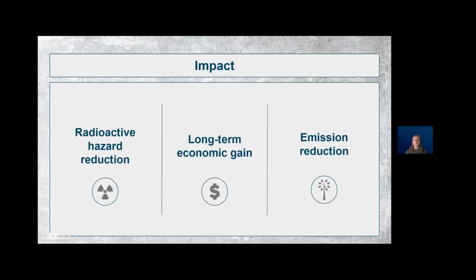Geopolymer cement addresses our problem statement by providing a material to replace ordinary Portland cement in nuclear waste encapsulation. This is valuable for managers of nuclear plants and waste disposal sites, as well as the surrounding community. Based on an investigation we conducted for a pilot project in Richland, Washington, benefits include a reduction in carbon dioxide emissions up to 50% and similar or lower annual operating costs.